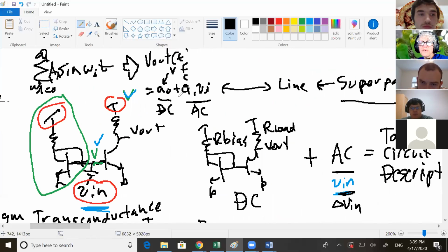So we have this equation right here. A naught, that's just a constant. And if you look at that in terms of the circuits that you've been building, that is actually your biasing circuitry. It sets a voltage on the input to your amplifier to induce a current. This voltage right here, that's your A naught. So if you're taking this equation and trying to apply it or match it up with your common emitter amplifier,